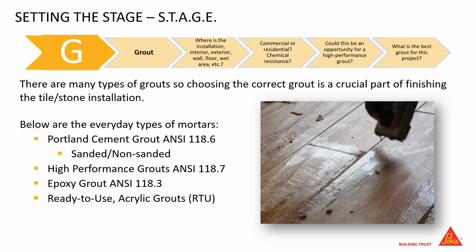Then of course you have epoxy grouts, and if anybody knows me, I'm an epoxy person. I love epoxy grouts. And then there's ready to use acrylic grouts. There's no real ANSI standard for that particular product at this moment in time, but I'm sure there will be. But they've really come a long way. They started off as a urethane, and they moved over to acrylic, so they're easier to use. But once again, you can use those in the wrong application. So we want to make sure that these products are being chosen for the right application and the right usage.